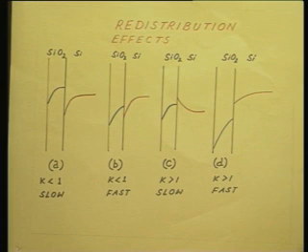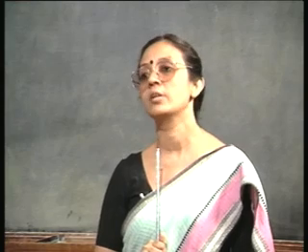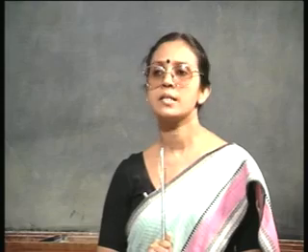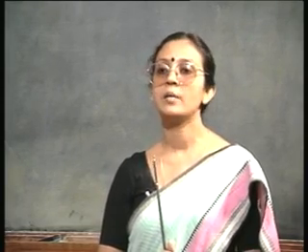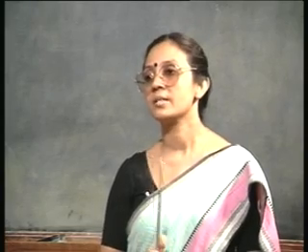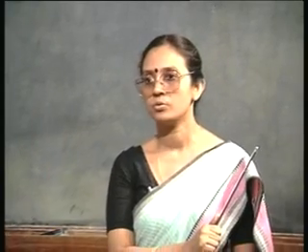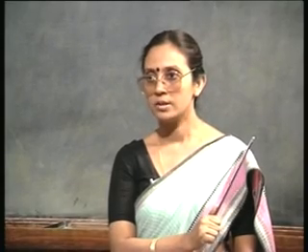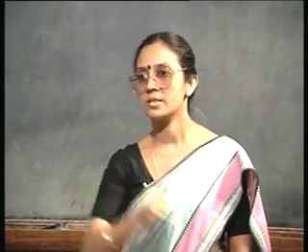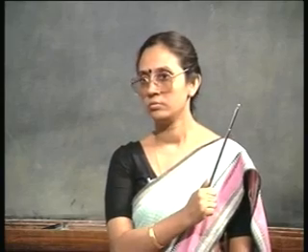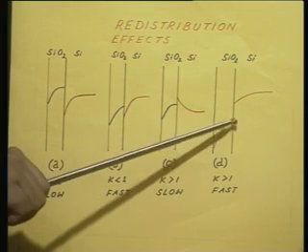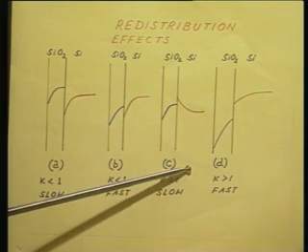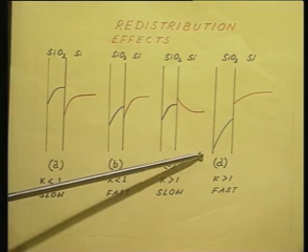That is because here the diffusion factor is going to dominate the phenomena. Gallium is an extremely fast diffuser. There is no chance for gallium to pile up at the interface. It just diffuses out. It just cannot pile up at the interface. It is forced out through the oxide. That is why, you see, inside the oxide, it just falls drastically. So sharply it is falling.